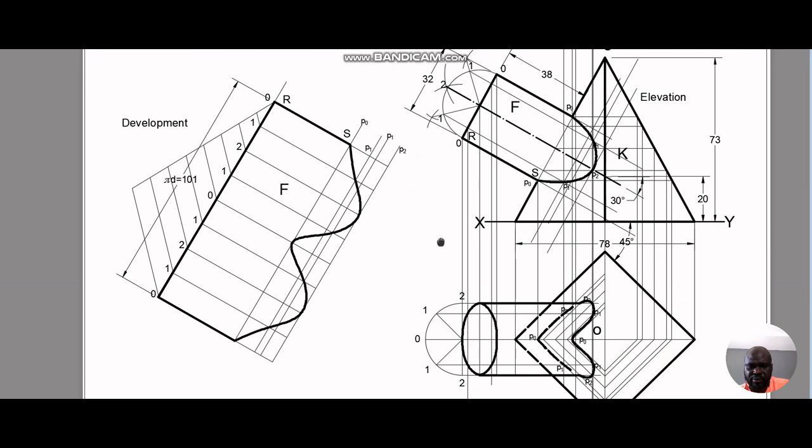So this is what we've been asked to do, to draw the curve of intersection, and whatever appears as curve of intersection in the front view, it will also appear that way in the plan view. And the pipe, if it's inclined, that inclined pipe would appear as an ellipse. It will appear as an ellipse here. And if you're developing this, you tear it open, and then you identify all the points that needed to be identified with respect to the circumference of the pipe in consideration. You will have this as your development.